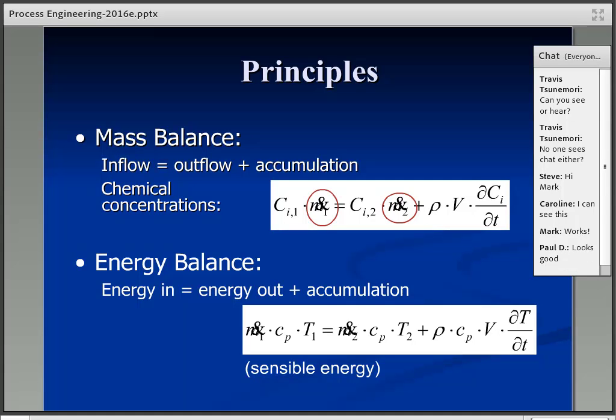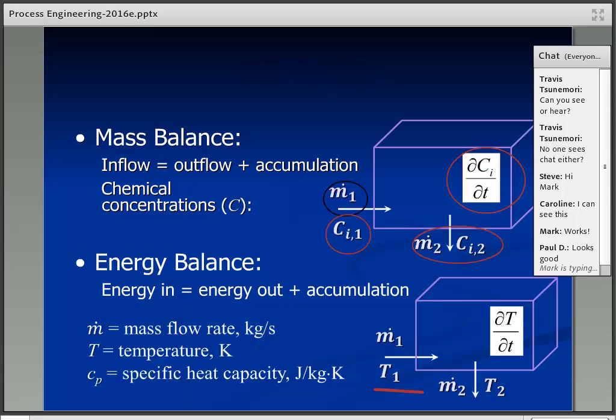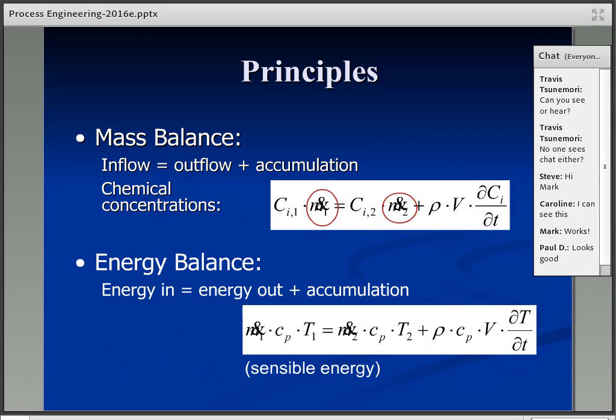Anyway, these are the general equations you can put together from that previous slide that we just looked at. I can go back here. That's all the terms defined on diagrams. Those are the general energy balance and general mass balance equations. You can apply them directly if everything fits, or when doing your own balance on typical problems, just write up your own inflow equals outflow plus accumulation balance.